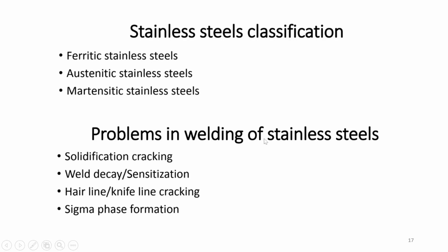Problems in welding of stainless steels. There can be solidification cracking, there can be weld decay or sensitization. Sensitization is the formation of chromium carbide. Hairline or knife line type of cracking, and sigma phase formation.